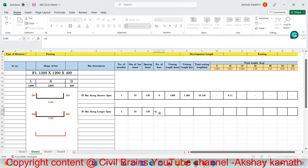So first you have to find I'm finding the bar along the longer span. So I have to take a shorter span. So shorter is 1200 minus 50 on the left side, minus 50 on the right side, bracket close. Put the divide symbol. Again, bracket open. What is the spacing? Spacing is again 150. Again, see, it got disappeared. It usually happens in Excel, not an issue. You just remember this H and this is 19. So write H19. So it will by default take that. Okay, fine. Now close the bracket. Okay, next plus 1 and close the bracket and hit the enter button.